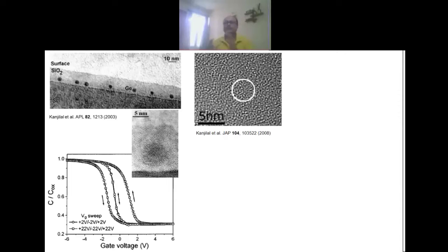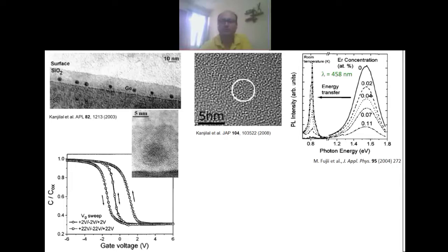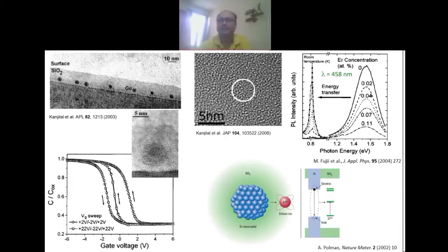Here I show a good example: these are high resolution TEM images I have taken from some paper. What is shown is that aluminum arsenide and gallium arsenide do not make that much strain. The lattice is almost close to gallium arsenide. So by taking the heterostructure, sandwiching this aluminum arsenide, there is no difference except the atoms will be different. Different atoms will be placed instead of the gallium. You are just placing aluminum, but it has different applications.